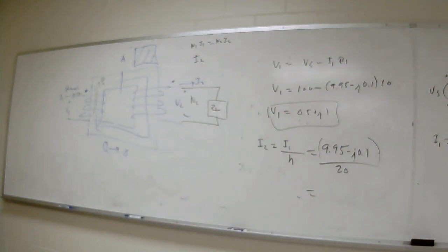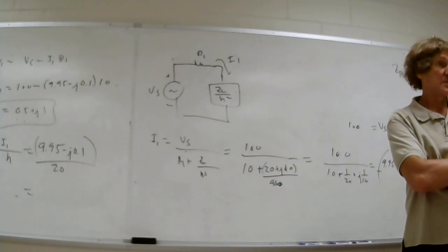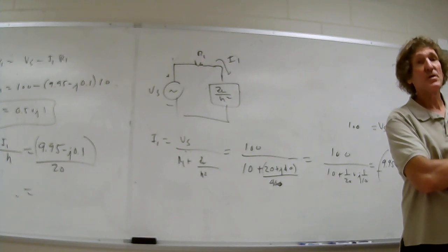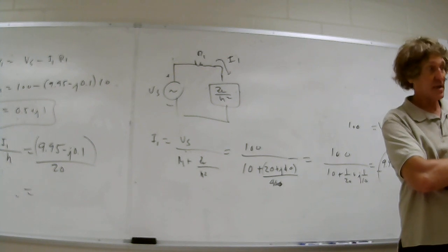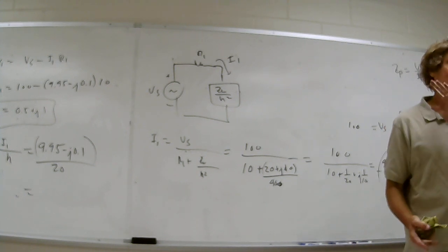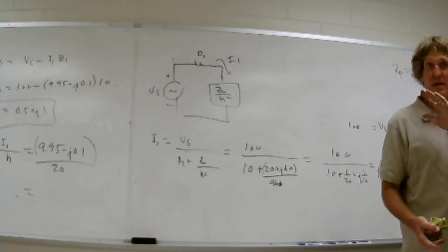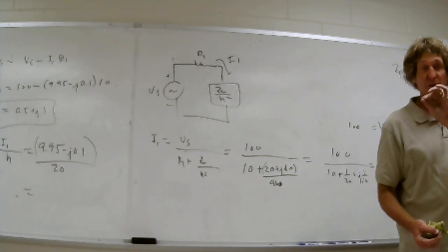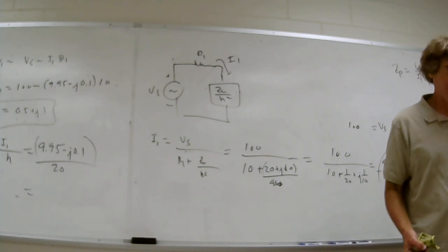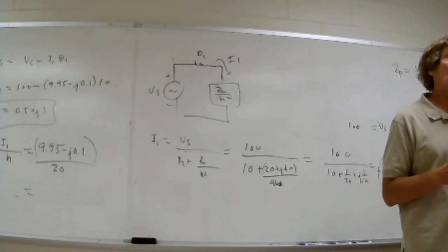Has anybody ever worked with any transformers in your life for anything? You know what a neon transformer is? You know what neon lights are, right? Yes. Those transformers take about 10,000 volts to light those things, so they take wall voltage and jack it up to 10,000 volts. The problem is now the current becomes very small. And neons sometimes draw some current, so they need big hefty coils on the primary and secondary. Well, the secondary not so much, but the problem is always losses.